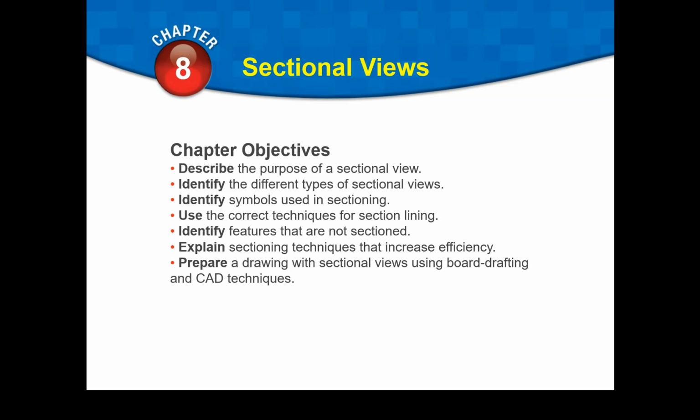Then we'll explore the different types of sectional views, from full and half sections to offset and broken out sections. You'll also become familiar with the symbols and the conventions used in sectioning, including proper section lining techniques to ensure your drawings meet industry standards.